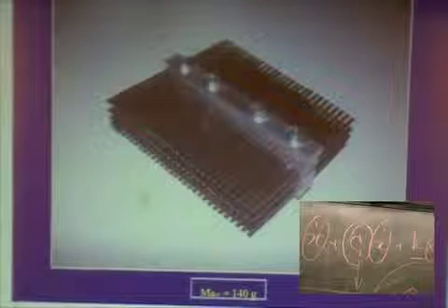And I would like to show what comes up. This is what comes up in terms of identification of the real apparent damping of the device. As you see, it has a sharp peak close to the resonant frequency. This is damping. It is not the frequency response, just damping, just this coefficient.